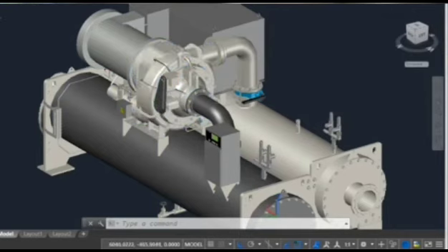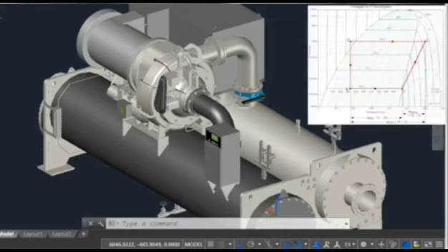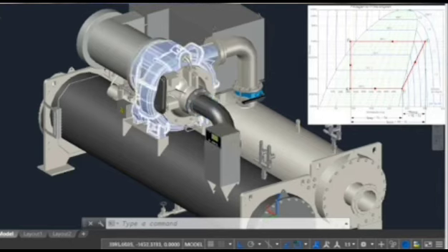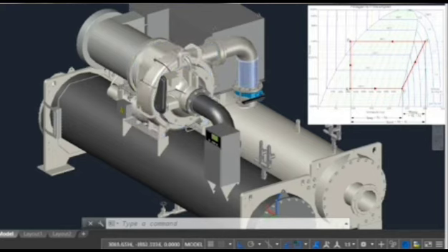There are different types of compressors like screw, scroll and reciprocating compressors. For larger capacities like 300 tons of refrigeration or more, the centrifugal compressors are selected. The compressor work is elaborated on the chart from points 1 to 2. The refrigerant enters the compressor in gas state at low temperature, low pressure, and it exits the compressor to the condenser at high pressure, high temperature.